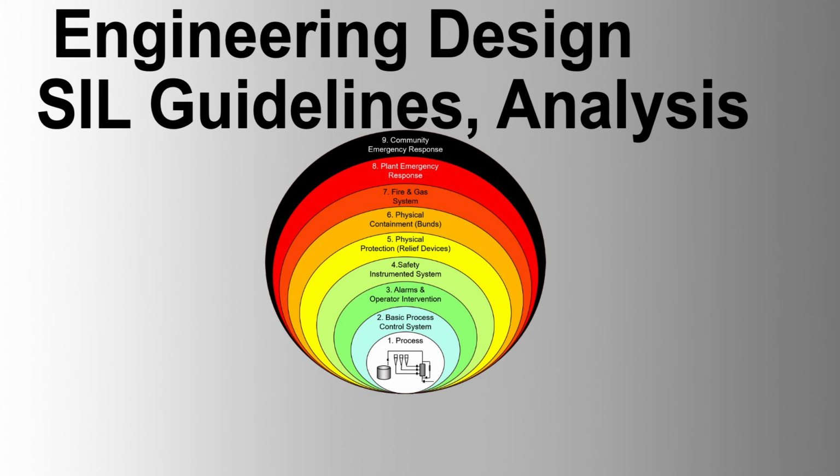1. Understanding failure rates. Failure rate. The failure rate of each component involved in the SIS must be determined. This can include both the dangerous and safe failures. Dangerous undetected failures: failures that do not get detected by diagnostic tests and can cause the SIS to fail on demand. Safe detected failures: failures that are safely detected and do not lead to a system failure on demand.